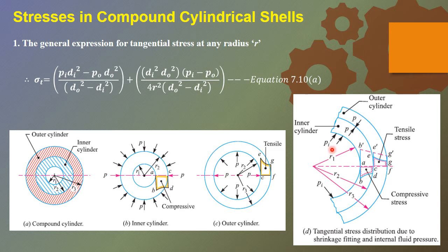So that is internal pressure, right? It was mentioned that once you load the cylinder and there is a certain internal pressure acting on the inside of the cylinder, it will first reduce or relieve the compressive stresses acting on the inner cylinder. It will first relieve the compressive stresses, and then it will induce the tensile stresses. So this is how higher internal pressures can be permitted in a shell by using the concept of two shells, that is, compound cylindrical shells, which allow higher internal pressures to be stored inside a cylinder.